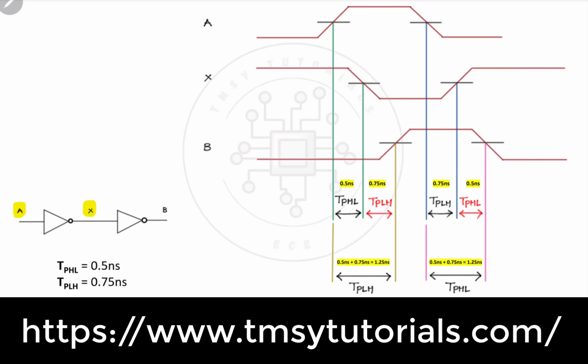Now this X will act as input to the second NOT gate where we get the output as B. Now at the X 50% point, draw a vertical line, and for B, the output, draw a vertical line. So here output B is changing from low to high, so it should be written as TPLH.